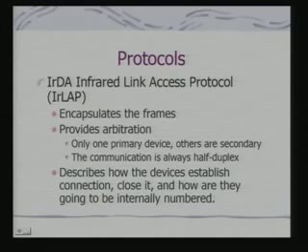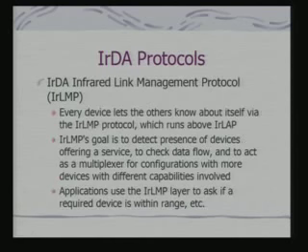What is interesting to note is that although it is not a host based kind of protocol, there is typically always one primary device and the others are secondary. On top of this, you have got the infrared link management protocol. So, every device lets others know about itself via this IR-LMP protocol, which runs above IR-LAP.